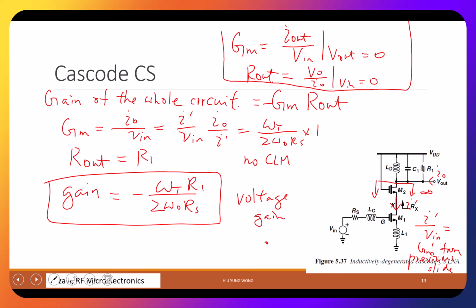Yeah, this is an intermediate node already. You cannot decouple them, because then this has a low input impedance, right? When your loading has low input impedance, you cannot just chop them. If you have very high input impedance, you can chop them into equations and do multiplication. And that's why we use current, because if your input impedance is 0, again, I can chop them into 2 parts.